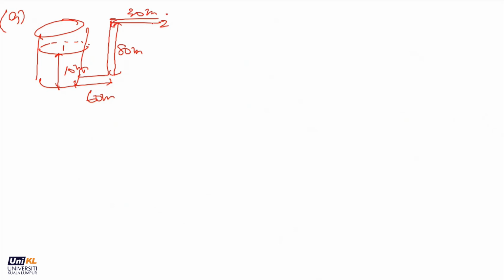Okay. Gauge pressure. So they want P1 here: what is the gauge pressure at point 1 to provide a 20 degree Celsius water flow rate Q of 60 meter cube per hour, and the viscosity of water at 20 degree Celsius is 0.001 kilogram per meter second.